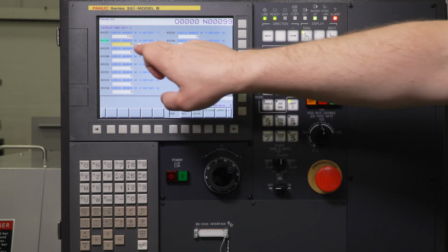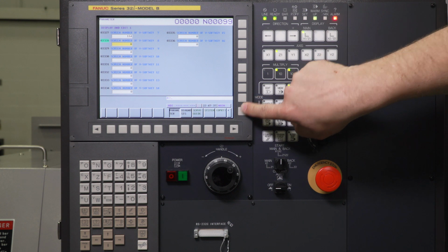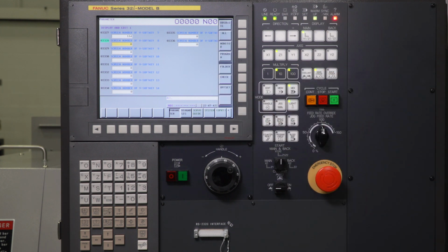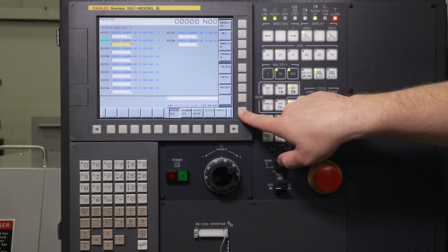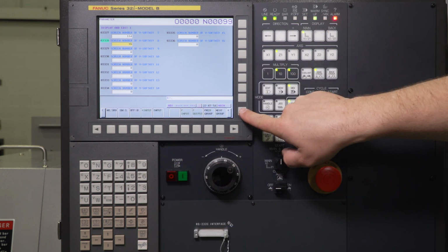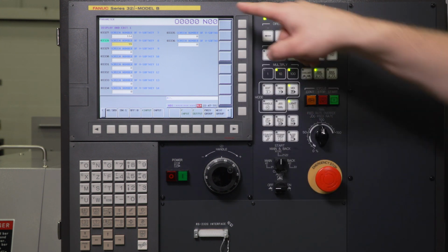3328. So this is vertical soft key number 8. So that would be number 8 here. This one has to be set to 99 in order to get to page 2. So if I don't make this a right arrow, I can't get to page 2. So if I make this a 99, input, and now I press this, now I have a little arrow here. That's going to allow me to get to the next page.